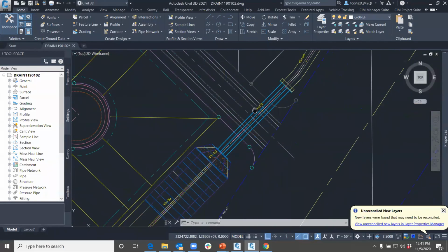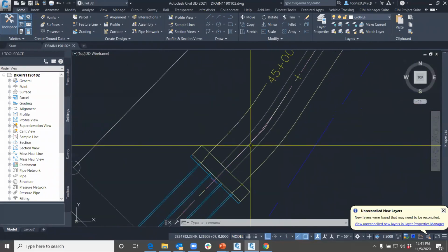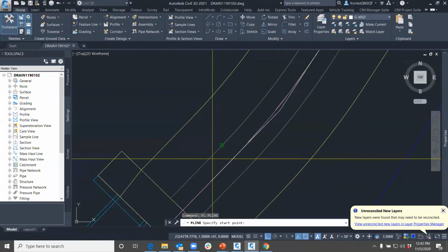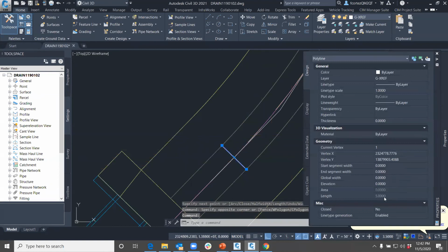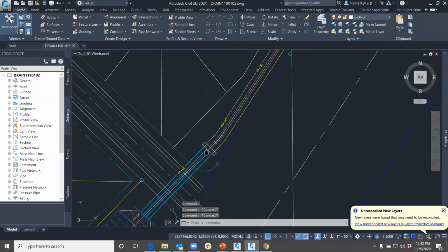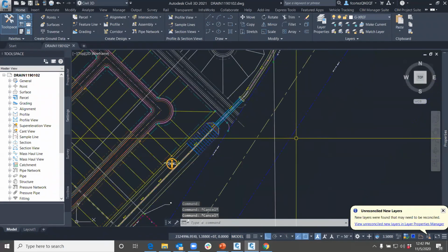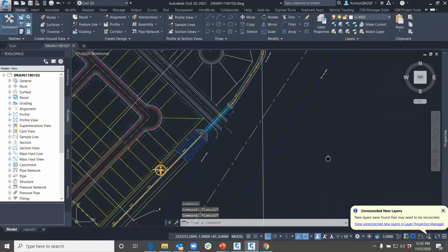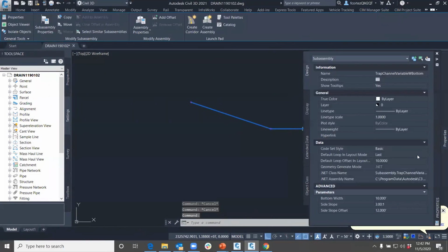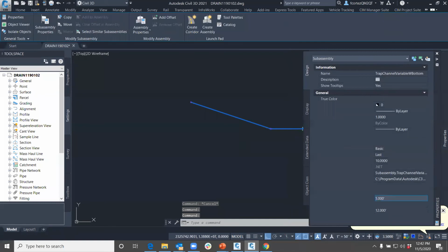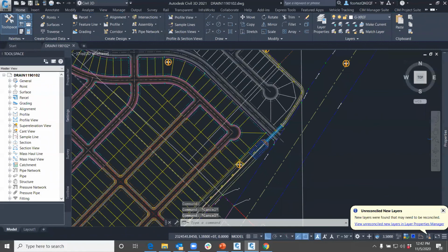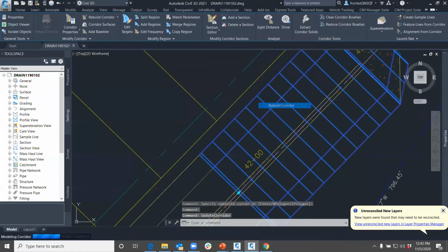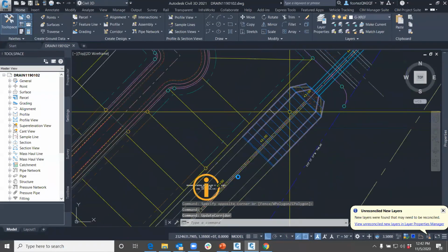And just to show how versatile this is, let's see how wide this channel up here is. It's only 5 feet wide. So since this is using targets, I can come over here and tell this one, I only want you 5 feet wide. And even if I rebuild this corridor, it's using targets, so it's not going to overwrite that.